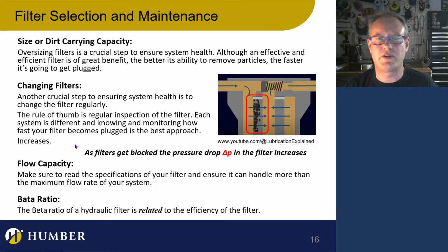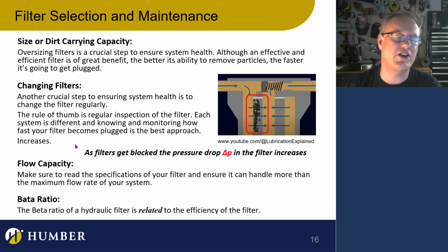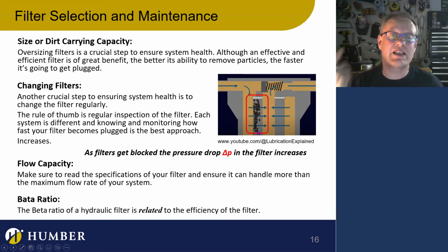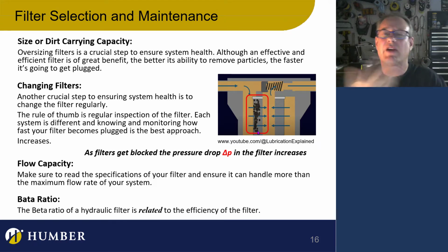Now, let's talk about these contaminants. Again, I'm going to do a whole bunch of slides on different ways of measuring the cleanliness of the fluid. But essentially, it's important to keep your fluid as clean as possible. But I want to talk about the dirt carrying capacity of a filter. The dirt carrying capacity of a filter is really important for your system because it has to do with pressure losses and energy losses and a whole bunch of things. So what's going on here is the filter itself. If there are particulates in the filter, and there will be because that's its function, it's kind of a catch-22.